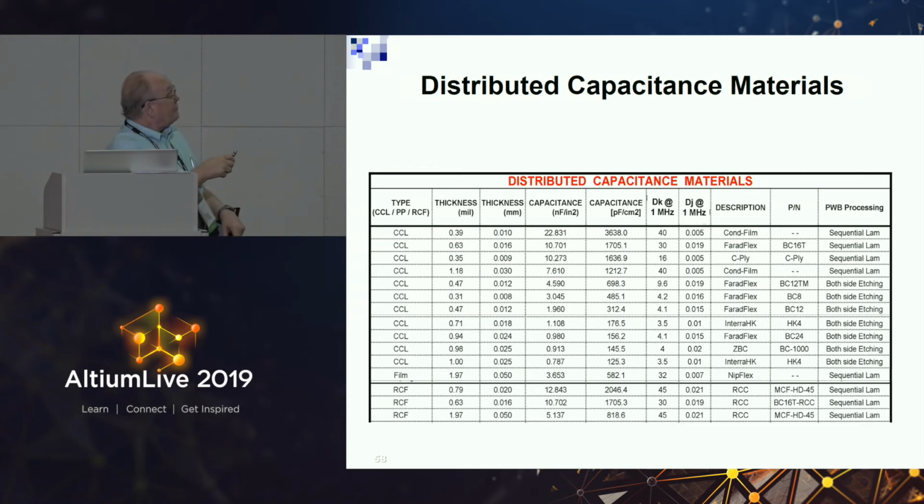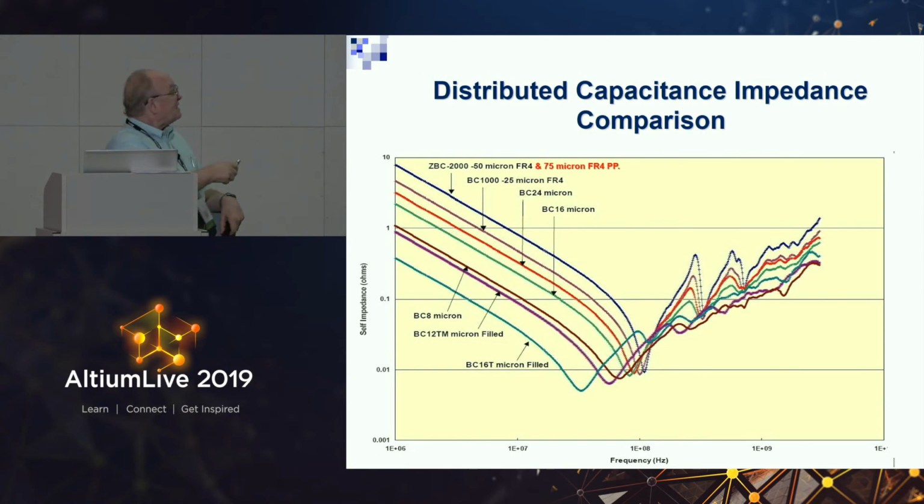And the best is the most expensive, the 3M at the top, and it goes down. What that does is it looks like this. These are capacitors, but this right here is a power ground pair. And the only way you're going to handle the lower inductance at the higher frequency is a power ground pair. I don't know how many of you use power ground pair, but you're going to get used to using it more and more and more with the newer chips because of the reduced noise budget and the shunting of high frequency noise.